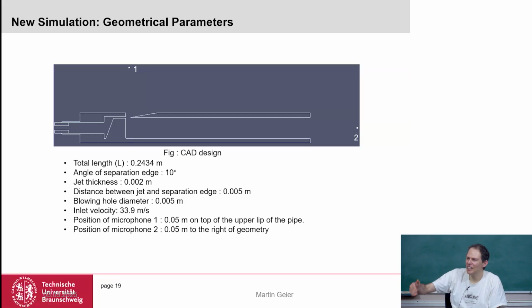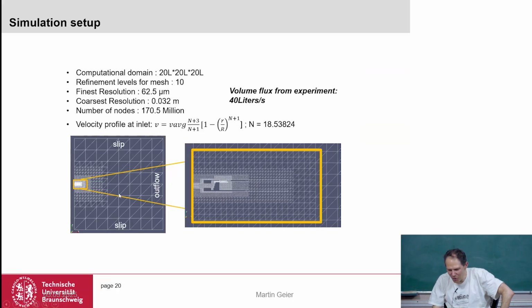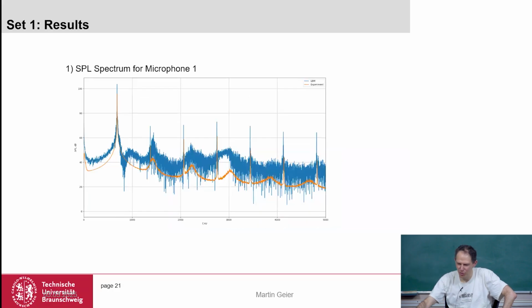And you want to hear the sound in the room, so you have to get this to the room. So what you end up with is that we use 10 levels of refinement, exponential refinement. So the smallest cell in here is 1024 times smaller than the largest, so that we can resolve the tip and the room. Okay, so this can be done in Lattice Boltzmann, and then you can measure the spectrum of this.